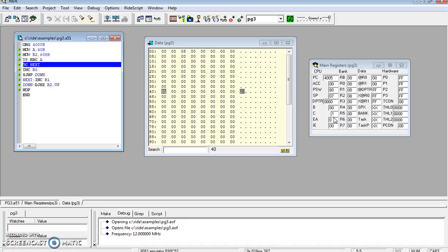It also indicates that the register holding the count of ones should be incremented by 1. So JC, jump carry: you check whether carry is generated or not. If carry is generated, it means we have transferred a 1. If carry is not generated, it indicates that we have transferred a 0.